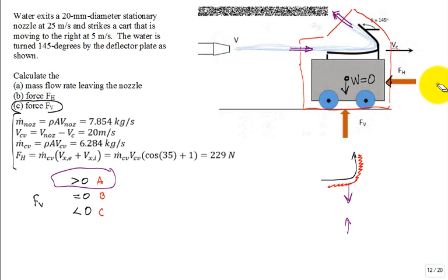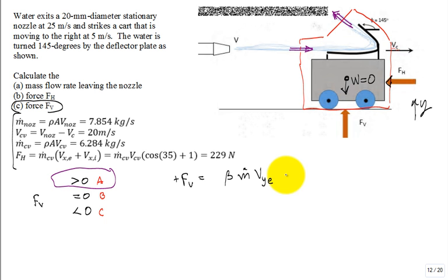All right. So now let's solve for and calculate F of V. So we apply the linear momentum control volume analysis for inlet fluid flow and outlet fluid flow for the control volume, and we have that this is a positive F of V because it's in the upward positive y direction, is equal to the correction factor, the mass flow rate, and then I'm going to put Vy exiting minus mass flow rate Vy incoming. One of those is 0. Which group is 0? This second group.